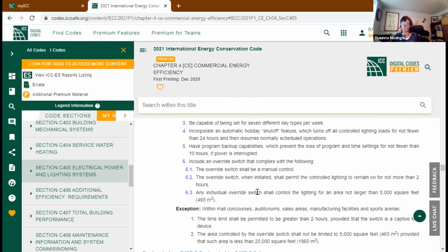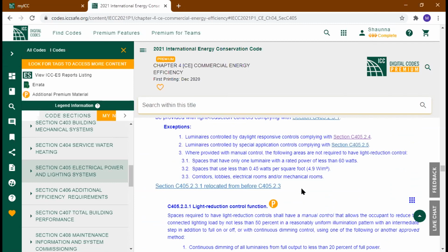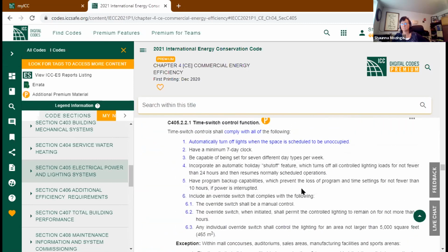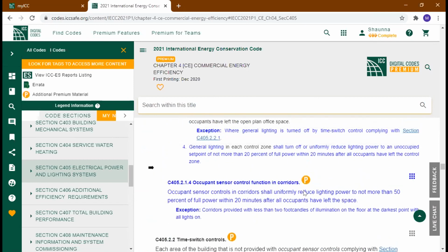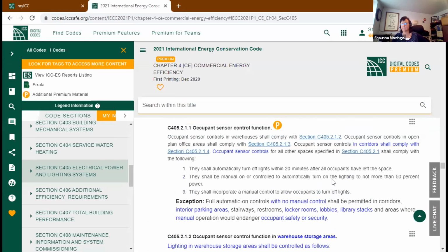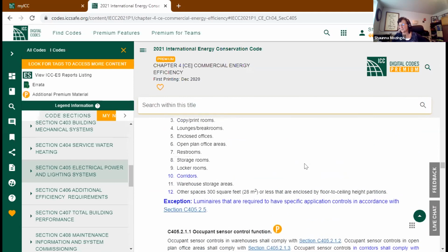It shuts it to 30%, right? It doesn't shut it off. So I could see that you could still use that to 30%. Yes. Yeah, that's one thing that I was wondering, because those parking garage stairs, you had like 15 to 20 foot-candles, but you don't want to use all that all the time. Right. So okay, those are things that I would definitely look at and say, okay, yeah, we want to save some energy, but we want to save lives first. Yeah, for sure. Okay.